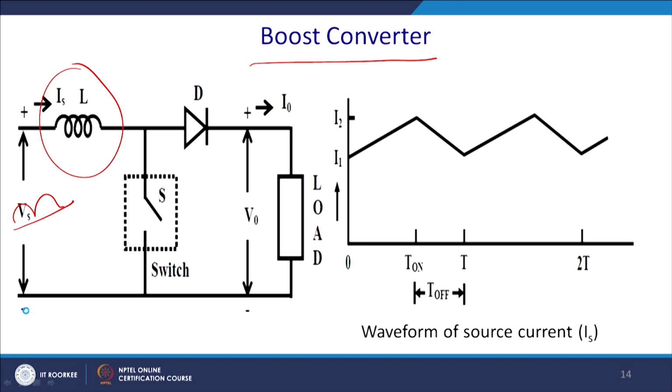We shall continue with the non-isolated DC-to-DC converter. We are discussing the boost converter. So, we continue with that boost converter. In a boost converter, essentially you will be boosting the voltage, and since one switch is on, the input current will ramp up through the switch,